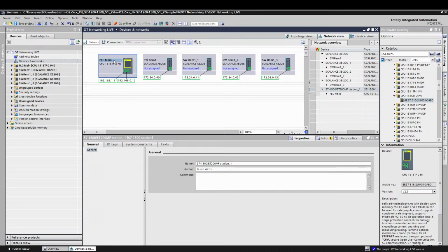And remember, if you notice, there are these stinking underscores. You know how much underscores are the bane of your existence if you are actually paying attention in Portal, because underscores are an illegal Profinet character. So don't use underscores. I don't know why it does that. Instead of using an underscore, use a dash. A dash is fine, not an underscore.